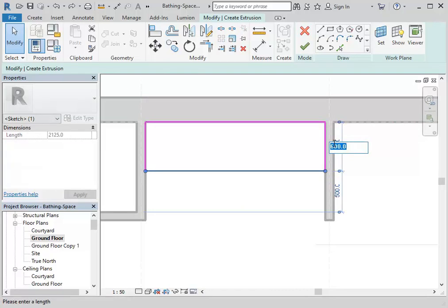and then give the size. Do you know the standard depth for a bench? You're on the right track. Yeah, 550 to 600, but 560 is good. So that's good. 900 is the standard height.